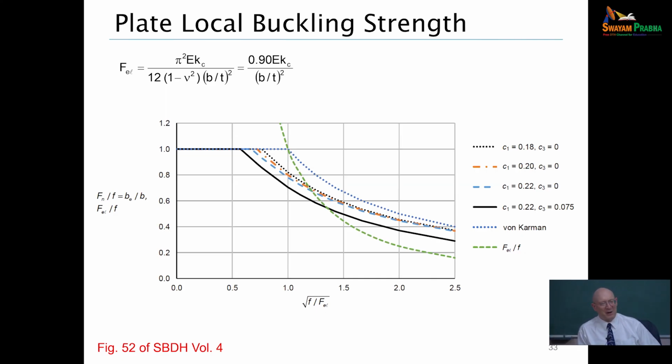After failures in the 1970s, there were actually some very expensive testing works that were done in the United Kingdom on boxes. And a lot of that work, I think they were being very cautious after those bridge failures in the 1970s, had recommendations. But then also there's some more recent German work that suggests that maybe Winter's equations were a little optimistic.